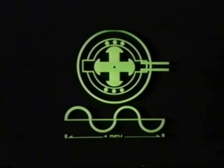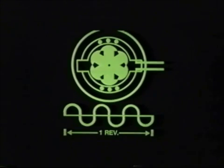For example, a two-pole field will produce one complete cycle per revolution. A four-pole field produces 2 cycles per revolution. A 6-pole field, 3 cycles per revolution, and so on.